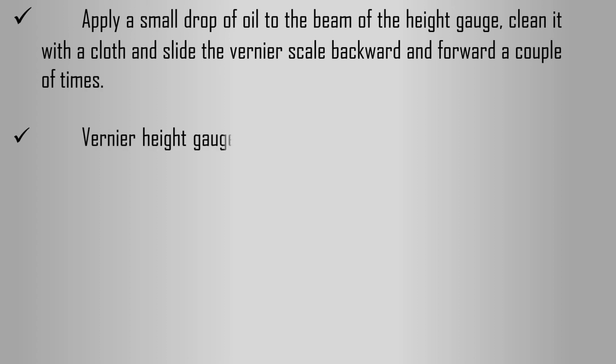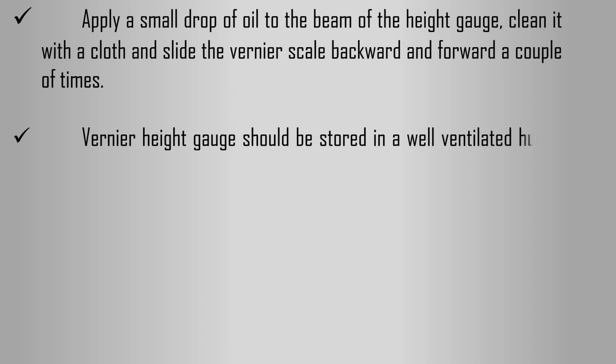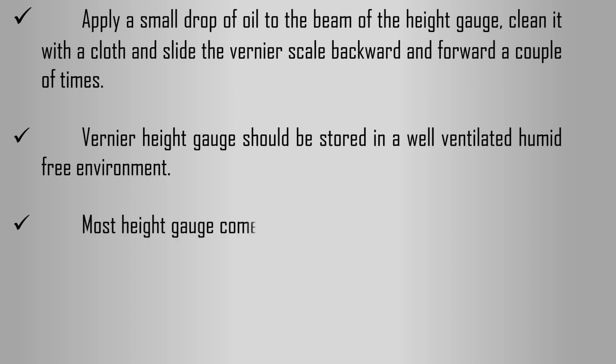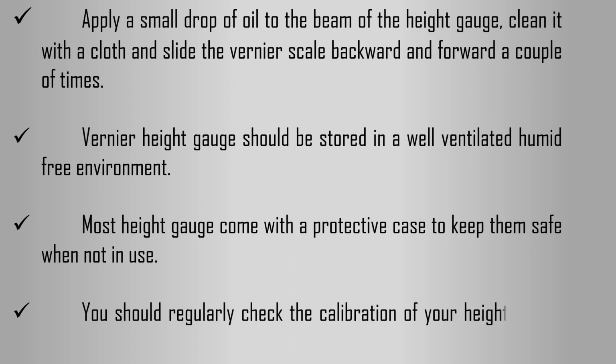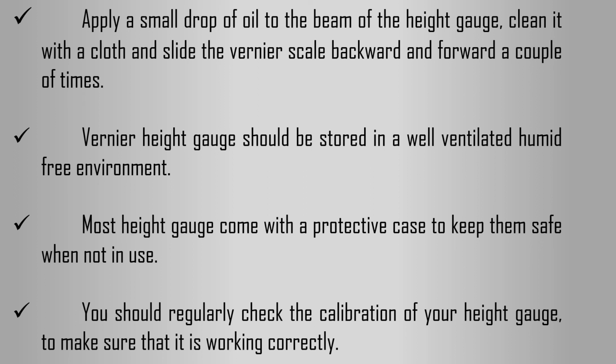Vernier height gauge should be stored in a well-ventilated, humid-free environment. Most height gauges come with a protective case to keep them safe when not in use. You should regularly check the calibration of your height gauge to make sure that it is working correctly.